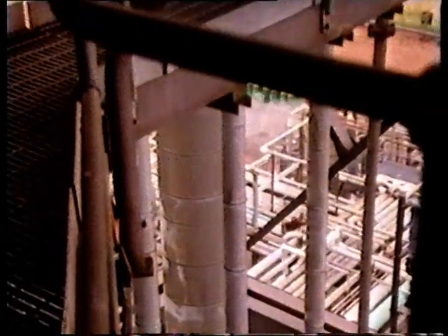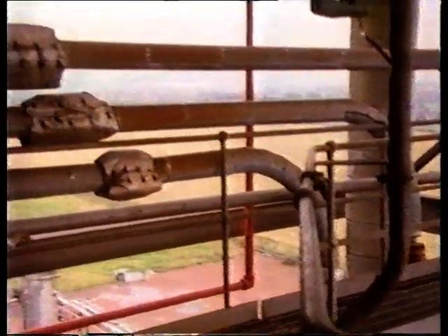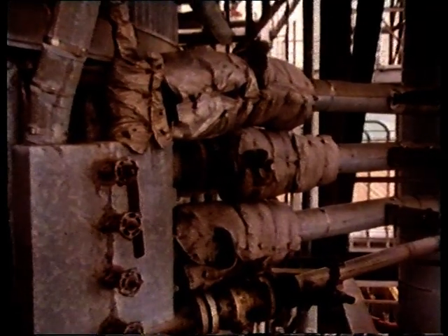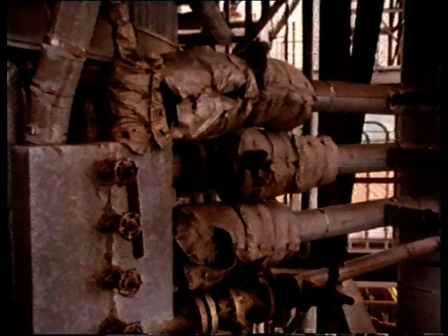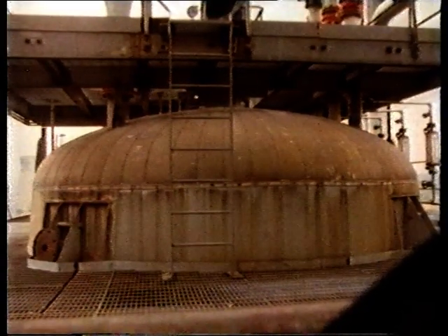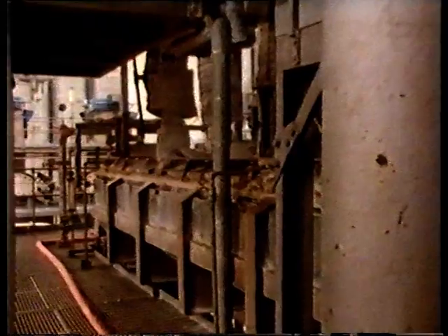The polyethene and carrier pass up these pipes into the flash tank, the pressure is released, and the solvent boils off with a roaring noise. The solid polyethene, a white powder, now passes down from the flash tank, and it's dried as it does so.